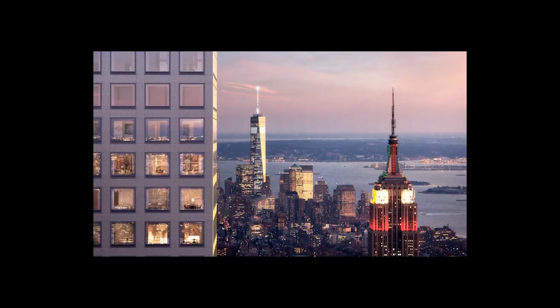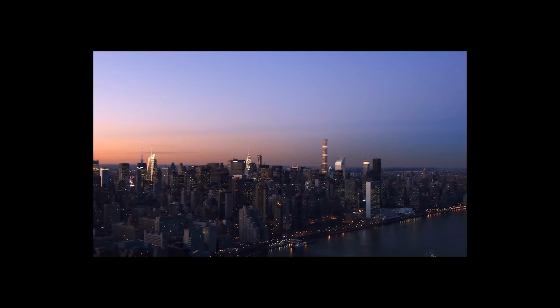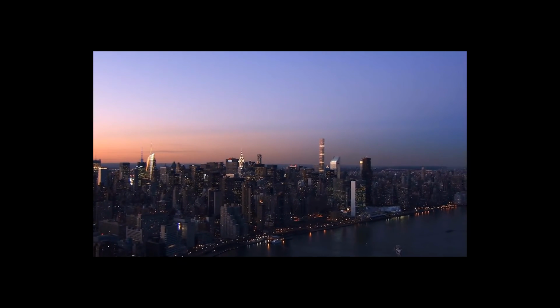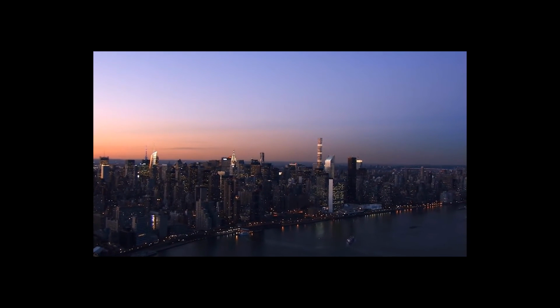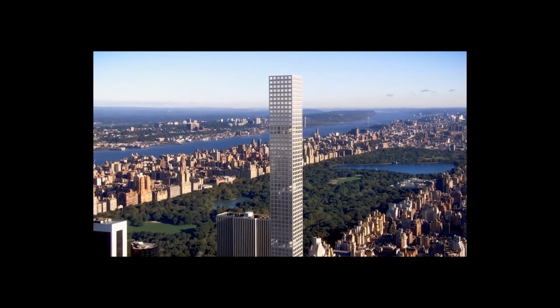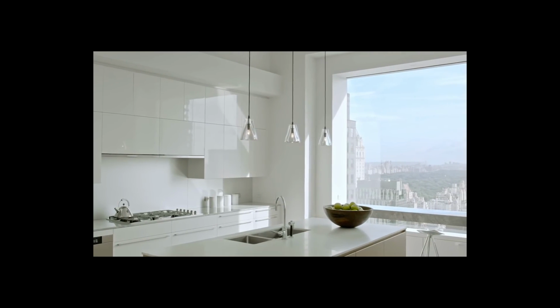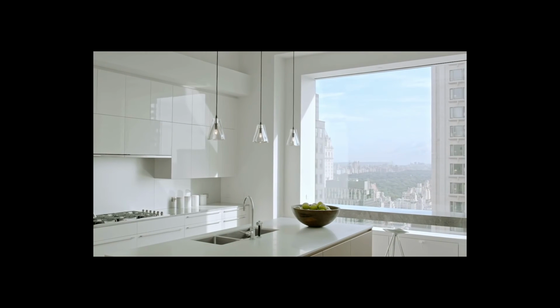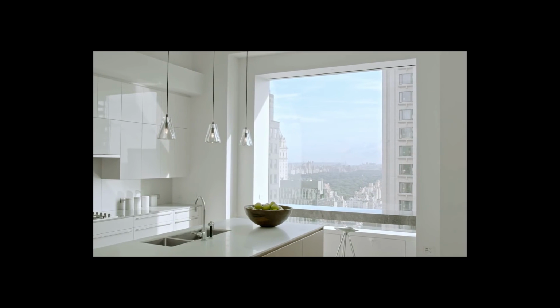In the tower, the same material is used for the exposed and the enclosed structure. Externally, the repeating concrete structural frames form the facade of the building and match the architectural intent of echoing the grid layouts of the city. The mix of concrete was especially prepared to give a smooth and white finish desired by the architect. Internally, one of the key architectural intents was to maximise the views. Diagonal bracing, which would have obstructed the windows, was avoided by using a rigid concrete frame system.